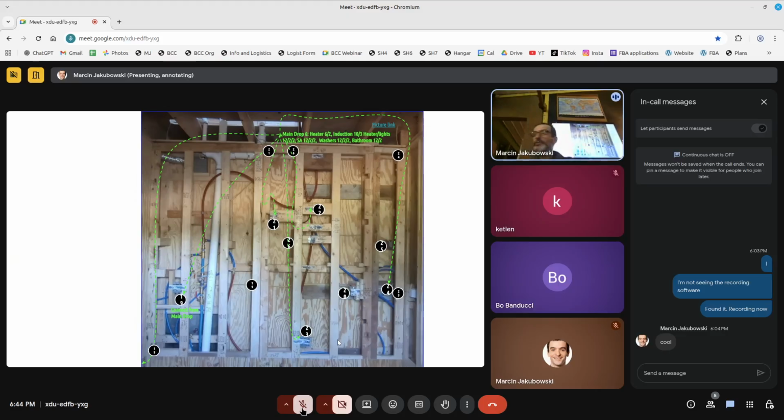We use a utility channel where, instead of drilling through walls, to save labor and optimize serviceability, we put a channel at the bottom. You can open that up and modify your wiring if you need to. For example, in the CDECO Home 1, we have a small utility channel, like a 4x4 cavity at the bottom of the walls, where we've taken wires in and out and threaded new connections. So it's actually very convenient.